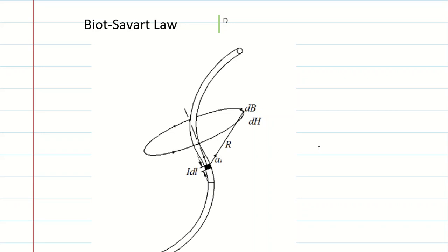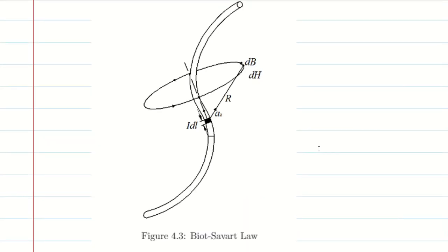It's magnetic field, so it's almost the same. If we want to solve for the magnetic field intensity, then we can use this one. To solve for the intensity at this point, we need to solve for the contribution of all very small cuts of this line. We cut them into very small differential lengths. Then we solve for the effect of each one. Later on, to determine the total magnetic field, we just add them all.